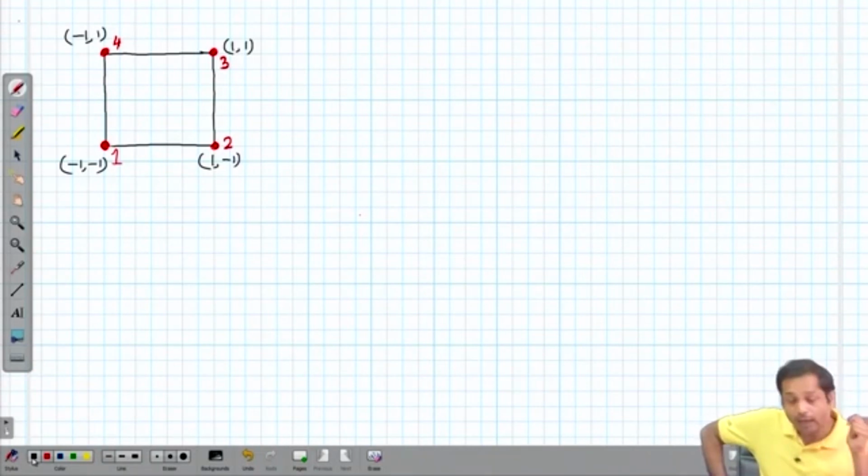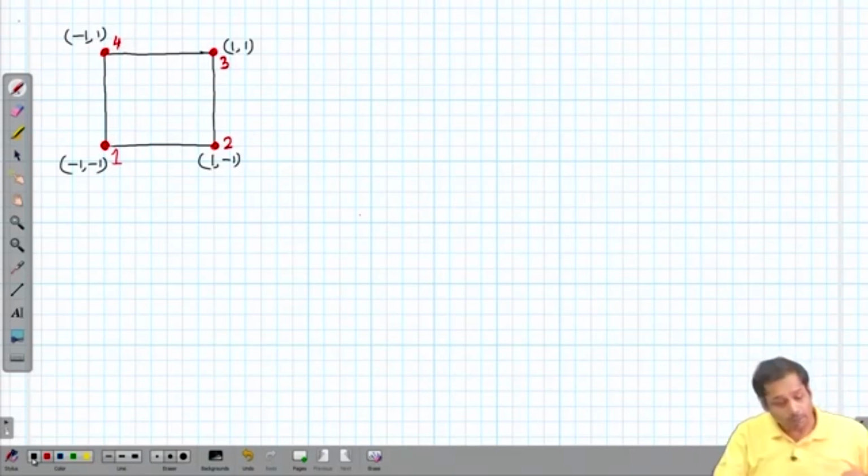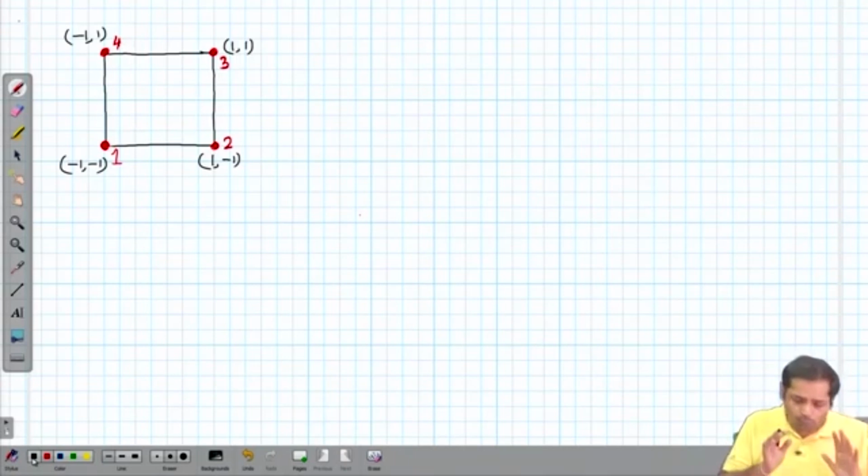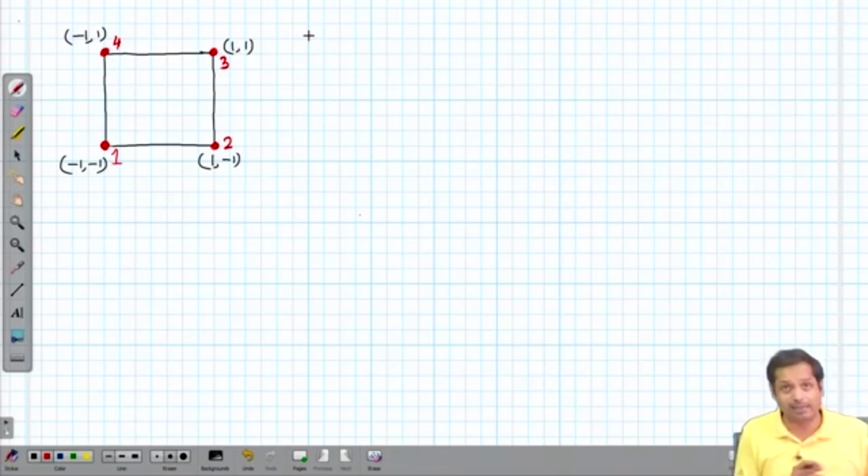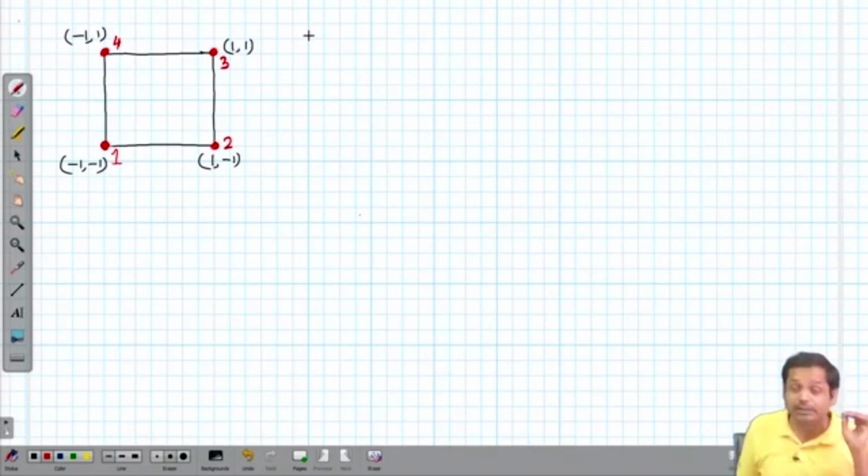Okay, now our approach will be slightly different. And what is that approach? What we know? Suppose I want to find out the expression for N1. Now what properties must this N1 satisfy? The important property is the Kronecker delta property, the interpolation property, because that is the only constraint we use in Lagrange elements, in the elements in the Lagrange family.